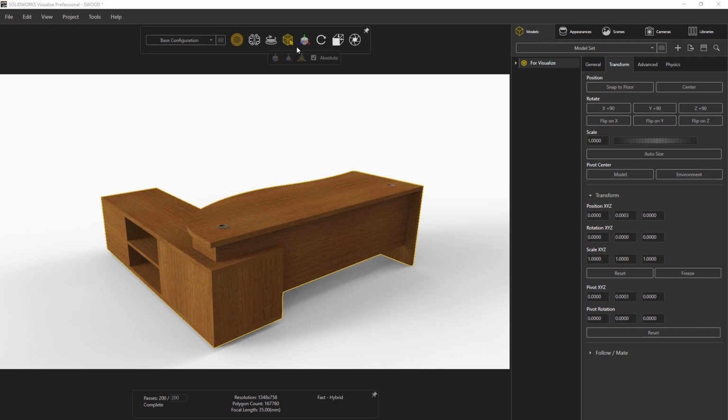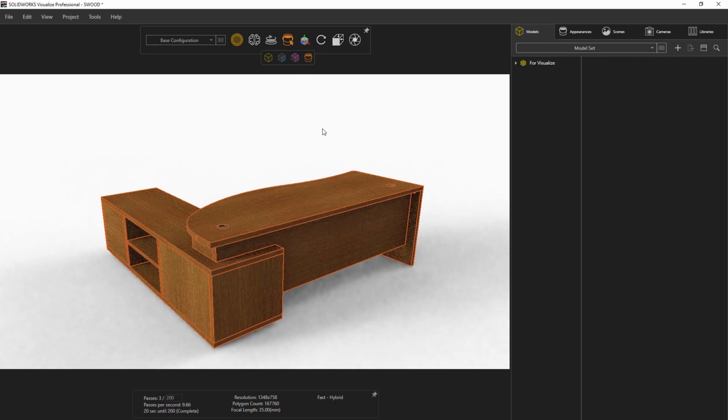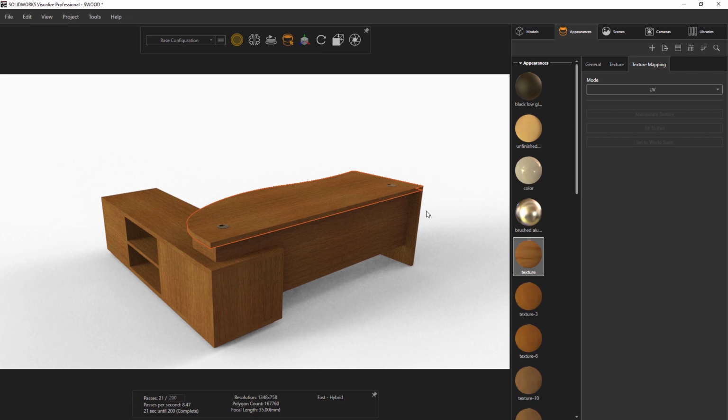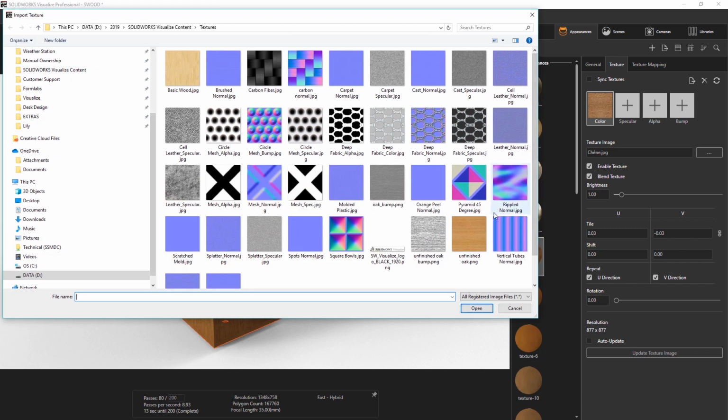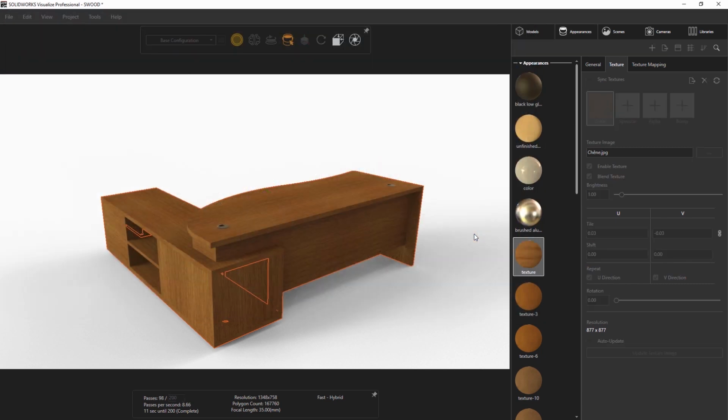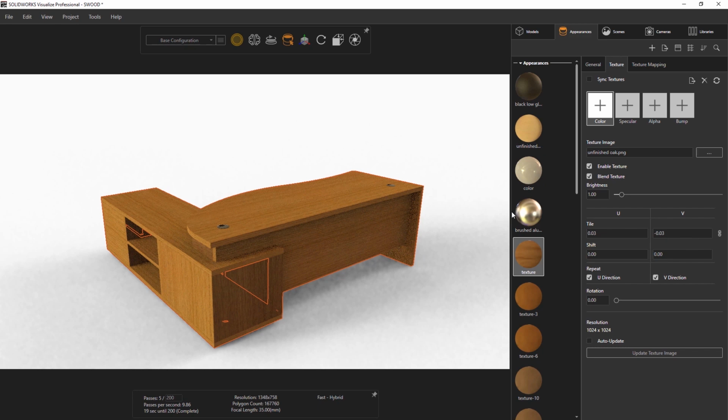Once imported, I'm going to change the wood texture. Although okay, Visualize allows more control of more advanced appearances. Instead of the dark wood, I'm going to use a seamless texture of finished oak. As a side note, always ignore the name of the texture or appearance. Although a good guide, rendering is all about what it looks like, and therefore try a few random woods.